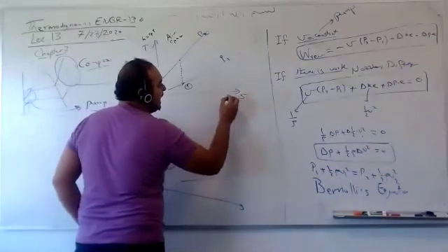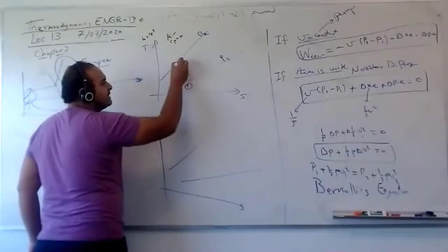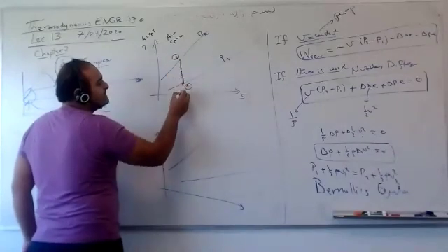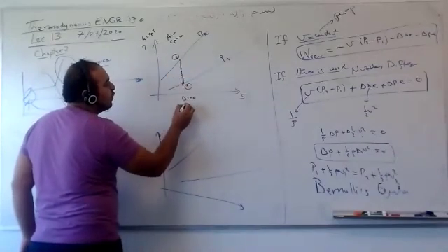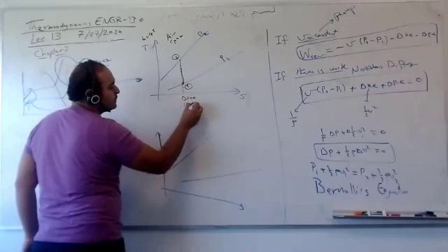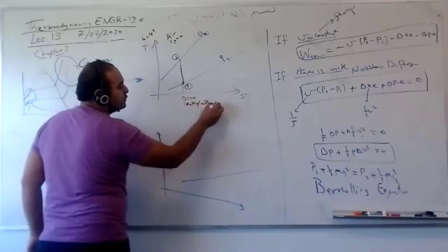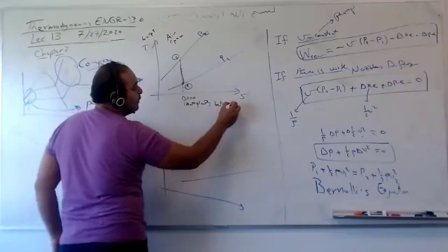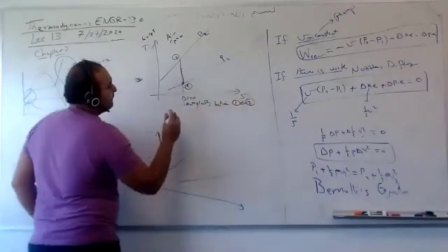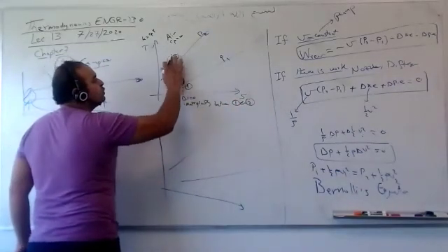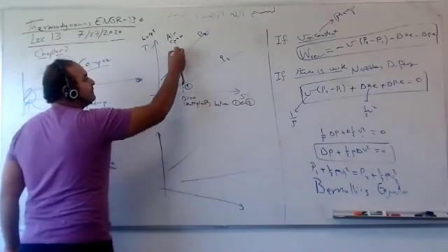If this is the Ts diagram, I wish to move vertically exactly like this, with delta S equal to 0. I wish to go isentropically between 1 and 2. That's a wish. We call it 2S.